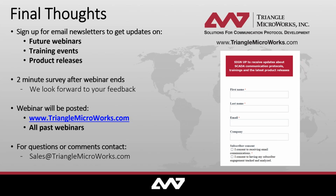But then it also indicates a lot with regard to the engineering flexibility. Depending on the device, and we will talk about that much more when we talk about the engineering in one of our future webinars, that's basically where the device declares how many report control blocks can be configured by a configuration tool, how many data sets it can have, how long a data set can be.